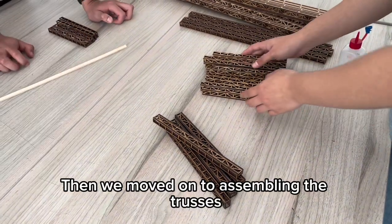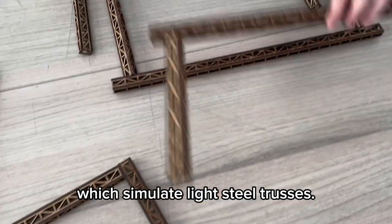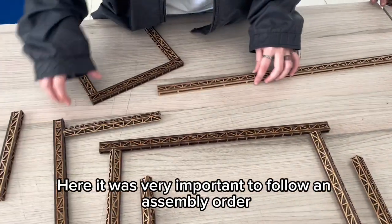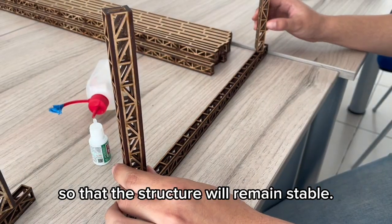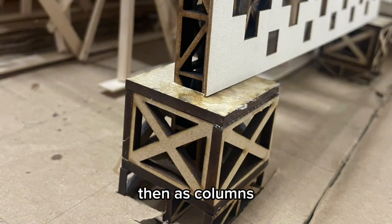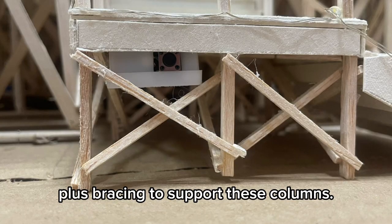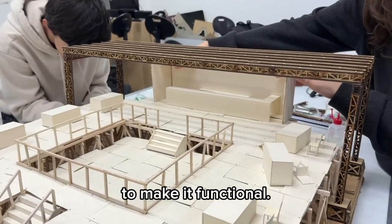Then we moved on to assembling the trusses with 3mm MDF, which simulate light steel trusses. Here it was very important to follow an assembly order and to check the right angles and alignment so that the structure will remain stable. The trusses were used first as a roof over a 30-meter span, then as columns, and finally as footings to simulate foundation, plus bracing to support these columns. At the beginning, the structure was very unstable, so we implemented this type of system to make it functional.